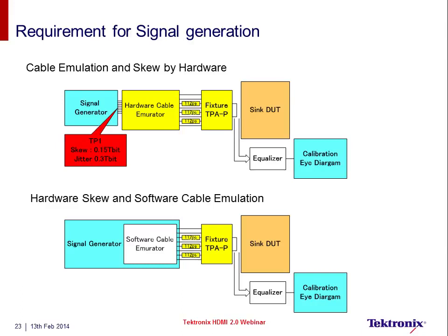Probably you will hear more about this in the coming months, but for now the cable emulator effect is part of the AWG. That means we are leveraging the direct synthesis capability of our solution, and we need the 112 picosecond delay line externally applied through hardware components before the signal is verified using a real-time oscilloscope. Once verified, we then perform the sync testing by connecting this impaired signal coming out of the HDMI signal generator to the sync device and performing the tests.